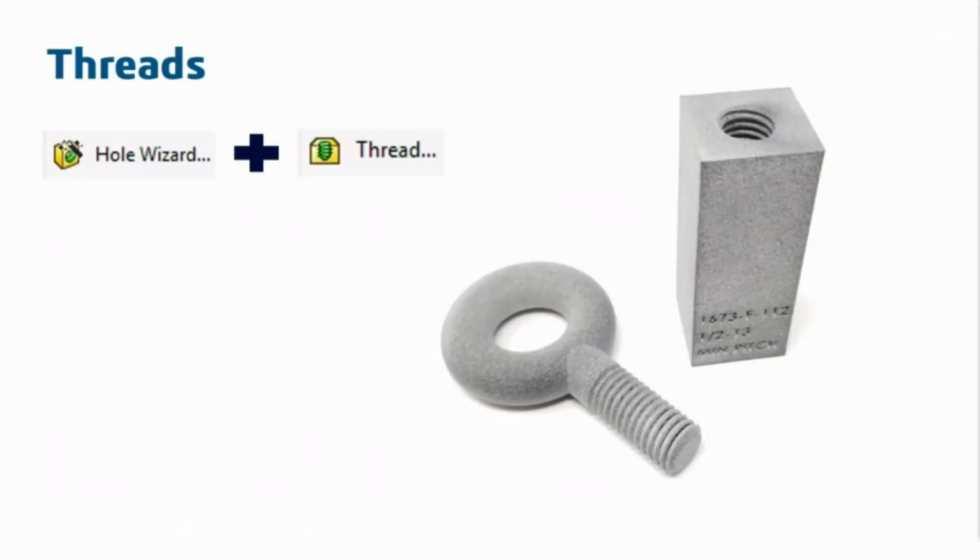Now, it's interesting here. You have a feature on here that I think I have told every SolidWorks user, don't put on your parts, and that is 3D threads. Tell me about the combination of Hole Wizard and thread here. Yeah, so we're all familiar with Hole Wizard. It's a really handy tool for putting in the correct tap drill size if you're going to send your parts out to a machine shop or something like that. Great for detailing. Snap a detailed callout to it. Boom, there's your hole size.